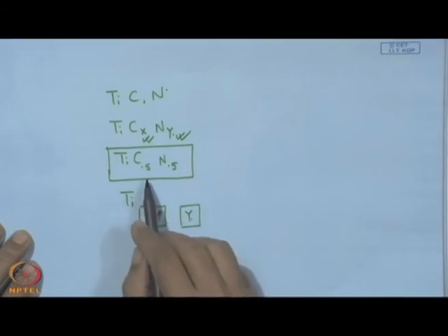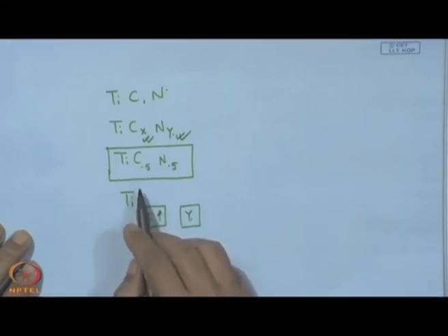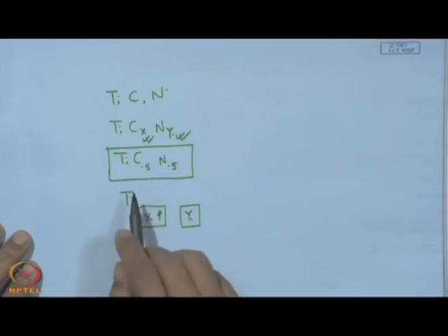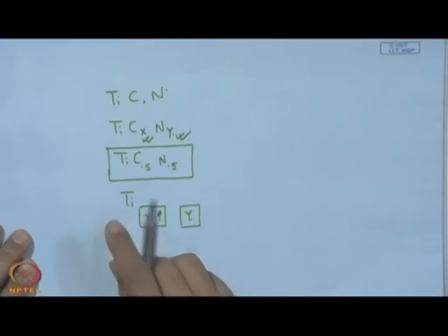Now, pressure can also have some influence, but the experience is that with rise of pressure, the coating becomes porous and less adherent. So the influence of pressure should also be considered if one has to make a good quality coating in terms of high density, good adhesion and adequate hardness of the coating.